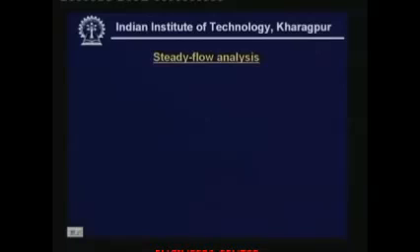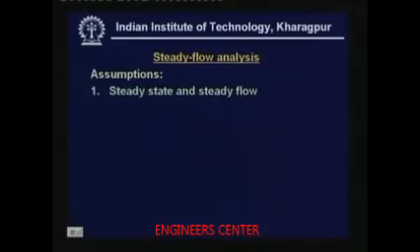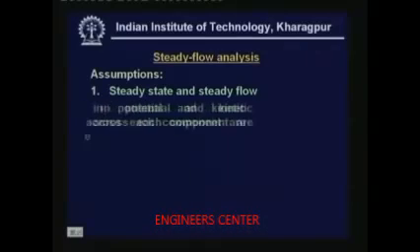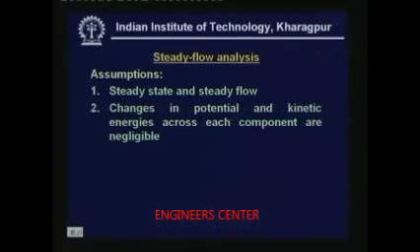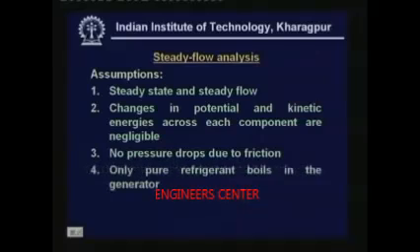Now let us look at steady flow analysis of a simple single stage vapor absorption refrigeration system based on water lithium bromide. First let me list out the assumptions made. The first assumption is a usual assumption: it is a steady state and steady flow process. Then changes in potential and kinetic energies across each component are negligible, and there are no pressure drops due to friction, and finally only pure refrigerant boils in the generator.